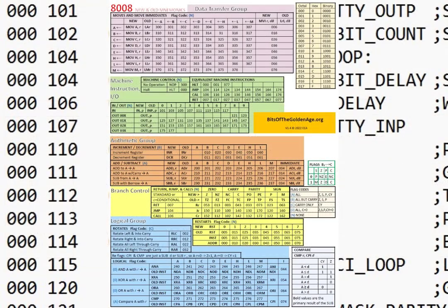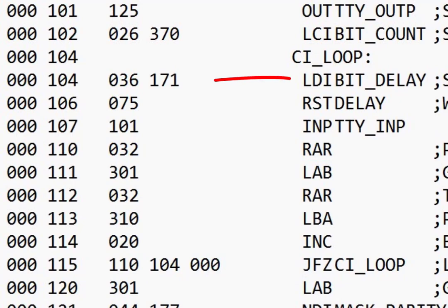and beyond. Now, I'm going into all of this instruction business because the processor needs to be able to handle every condition that comes along, and the number of bytes in an instruction is a big variable as far as the processor is concerned. Your program wouldn't get very far if the processor didn't know which bytes are instructions and which bytes were data. And that's exactly what would happen if it didn't know how many data bytes followed each particular instruction.